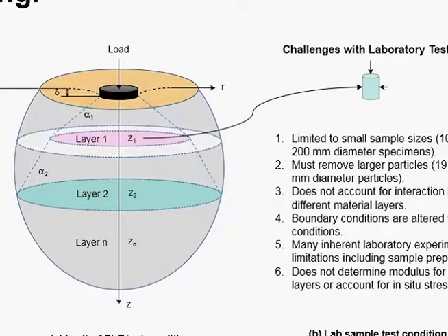We really like plate load testing. We've done a lot of other testing. We've done laboratory testing. We've done FWD testing, LWD, DCP, CLEG, and all the other devices. One of the reasons that we really like plate load testing is boundary conditions. In the field, we don't have to concern ourselves too much with boundary conditions. We measure what's there. If we do it at enough locations, we can get a pretty good idea of what's happening. When we bring materials back to the lab, things get a little bit more challenging.